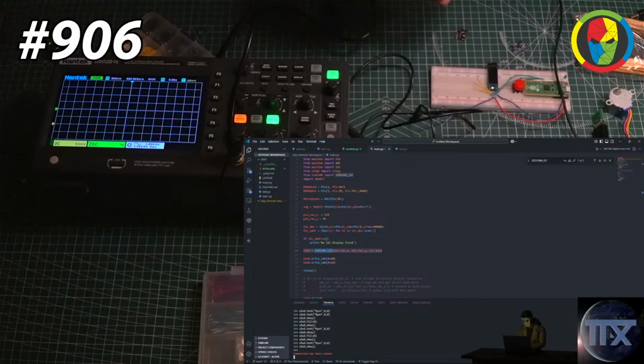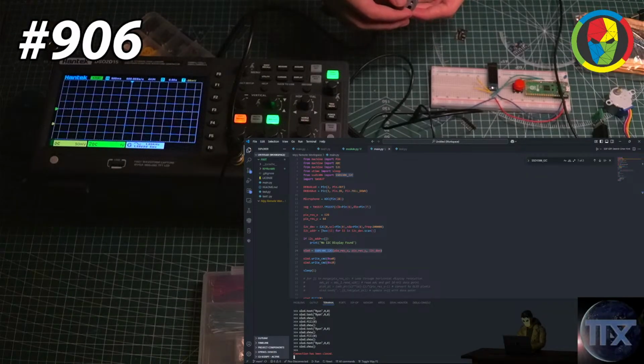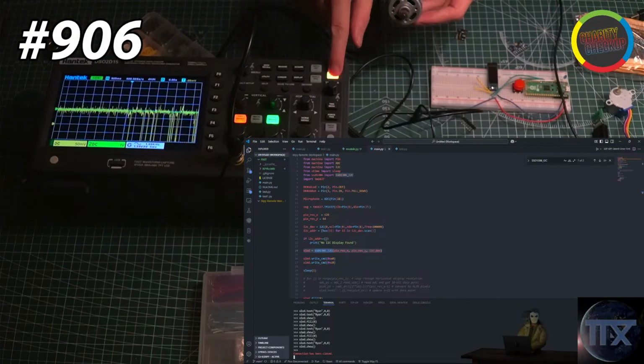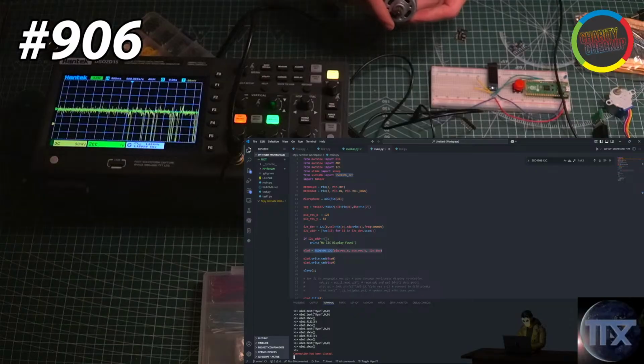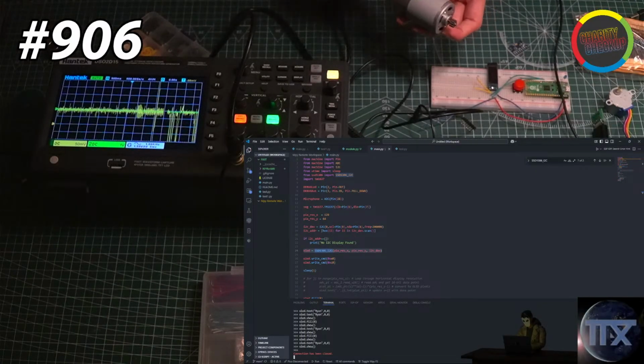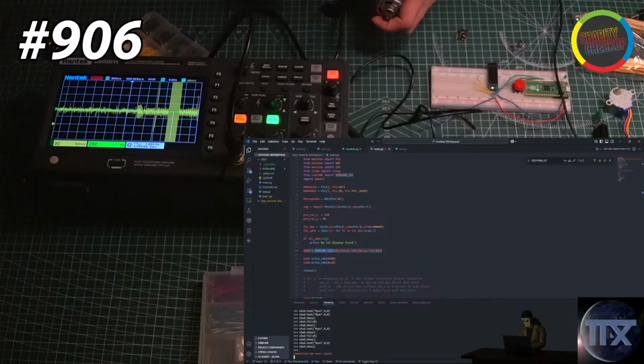And you talked about making a motor controller. So for a motor controller, you would use an oscilloscope to measure the output. And sometimes those are three phase, so you only have two channels, but they don't sell three channel oscilloscopes that I've seen. It's usually only one, two or four.